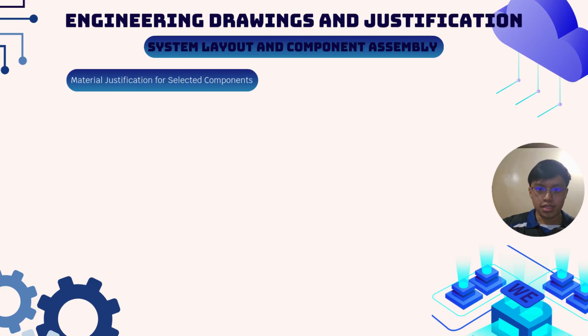Finally, the conveyor belt itself is a composite of industrial rubber and nylon ply. We specifically chose a rubber surface with a high friction coefficient of over 0.3 to prevent tray slippage and ensure efficient power transfer at our 0.7 meters per second operational speed. This combination of high-strength alloy and damping materials creates a durable, efficient system ready for industrial use.